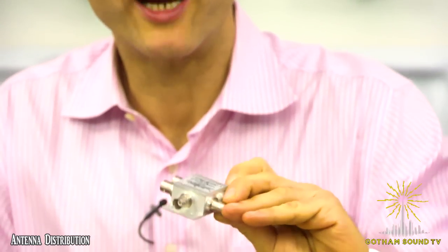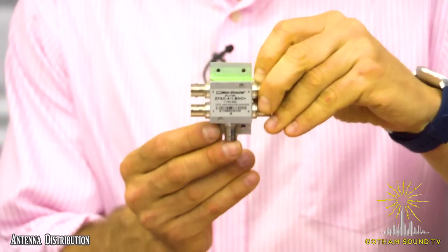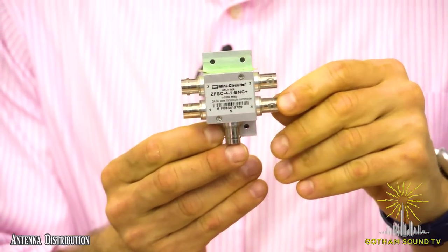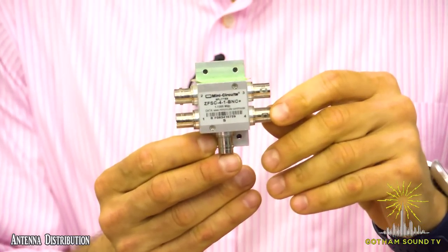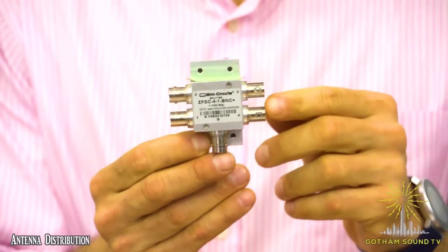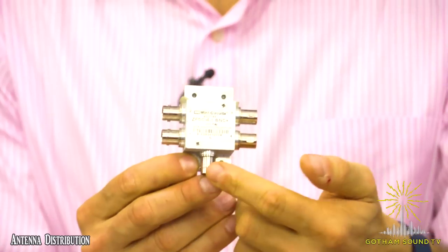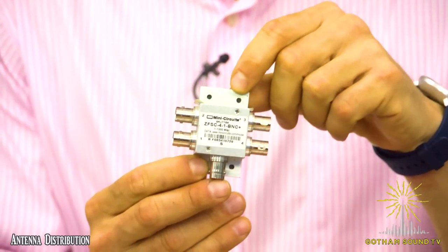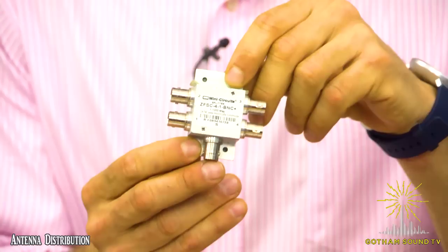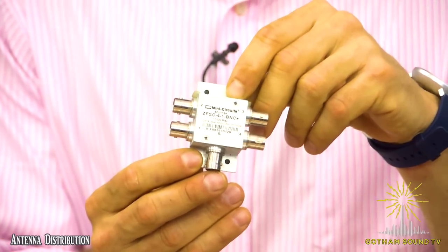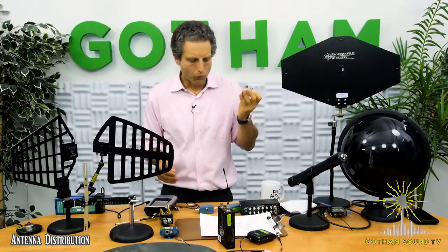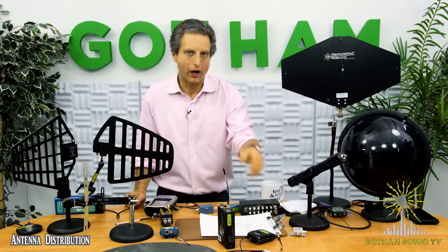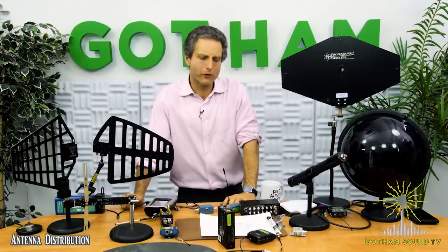Lectro distributes these, but these are from Mini Circuits, to make your own RF distribution for any use, but for bag use too. This is 1 in and 4 out, and it does provide sufficient isolation. You would obviously need 2 of these if you were going to use diversity. The splitter won't provide power to antennas for the amplifier and antennas, though.